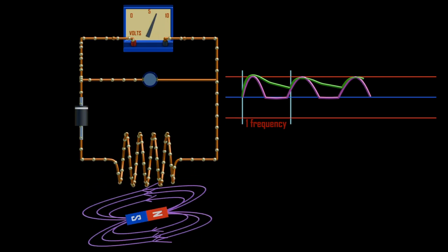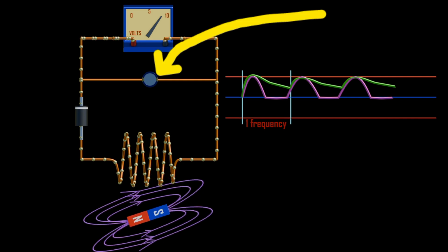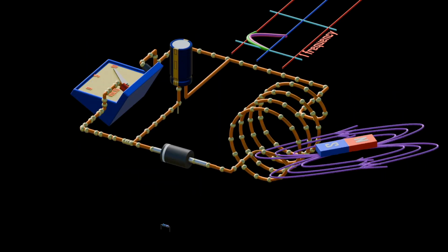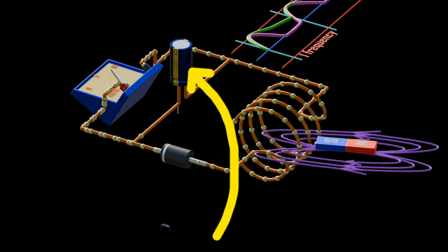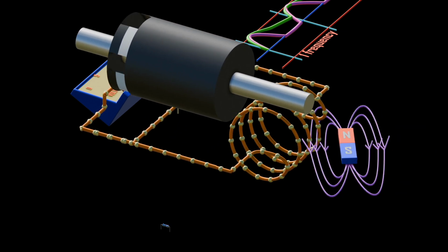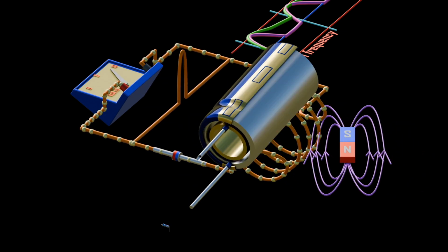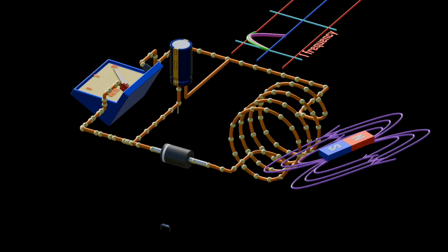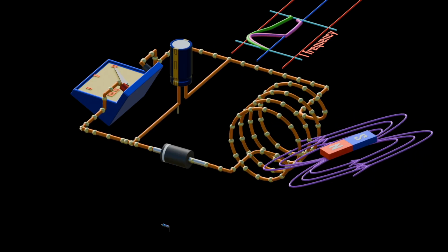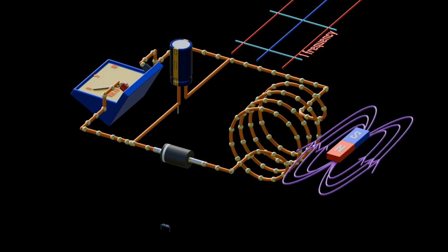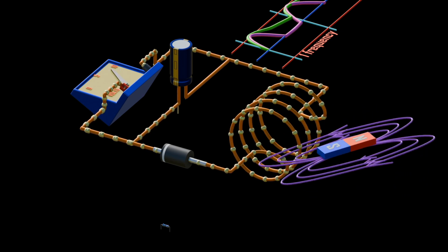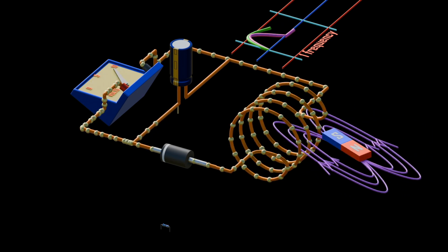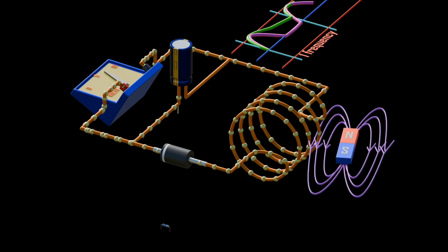For example, using a capacitor as a filter in the circuit, the ripples will be reduced. Capacitors have the ability to store charges and release them to the load. Check our capacitor and diode videos on how they work, link in the description of this video. In general, filtering is accomplished by the use of capacitors, inductors, and resistors. Capacitors are used as shunt elements to bypass the alternating current around the load.